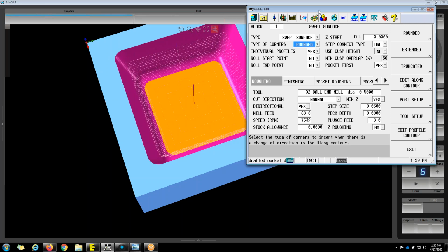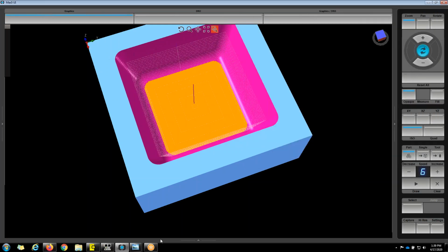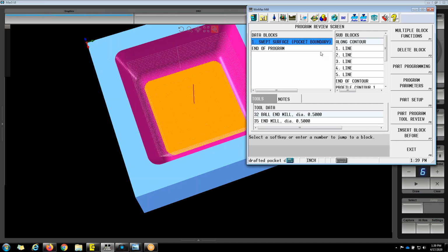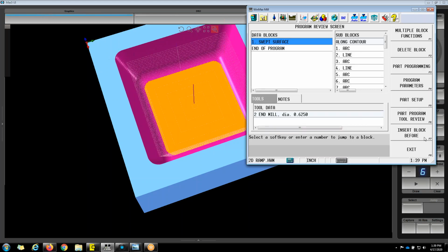The next one we had was on your little VM10 video where you were cutting the part. They asked if that could be done with a helix in lines and arcs. Well, explain why we couldn't. You could do part of it. Let me switch back to that, which is the part we just programmed. You could program part of it, and I have in the past done a helix to rough in parts that are a little bit more rounded.